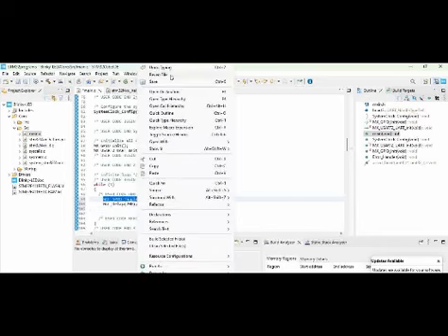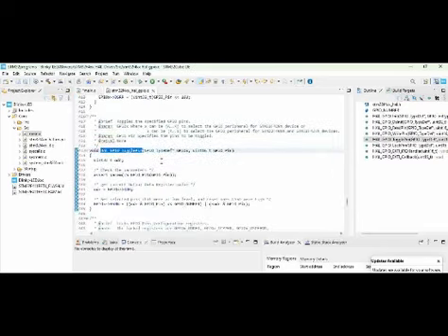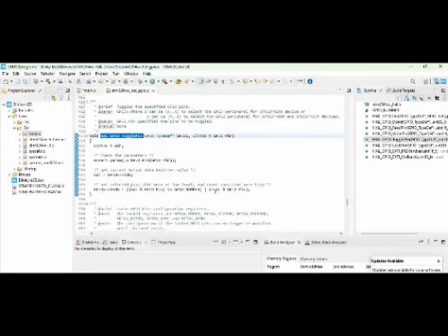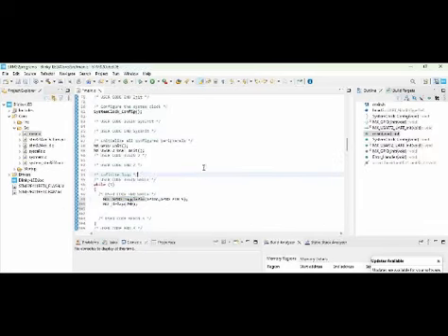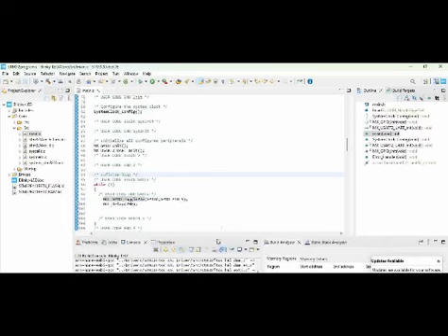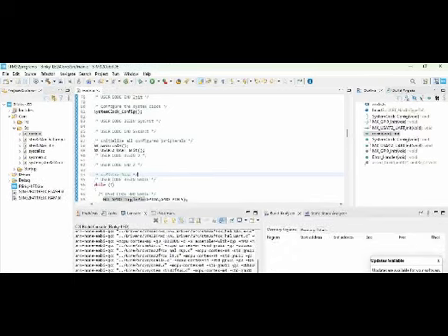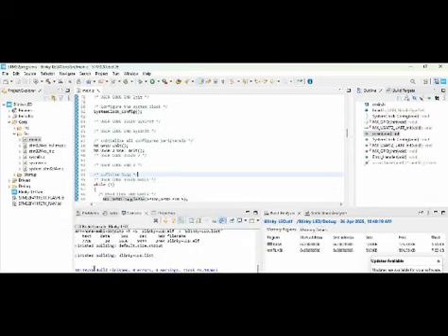If you go to the toggle function, you can see it just negates that particular pin every time. So first it will be high, wait for the delay, again the toggle pin function comes up, it toggles to low, again delay, then high. So the sequence continues. Once this is done, use this hammer symbol to build the project. Once you click on build, you see build finished, 0 errors, 0 warnings. That means you are ready to go.